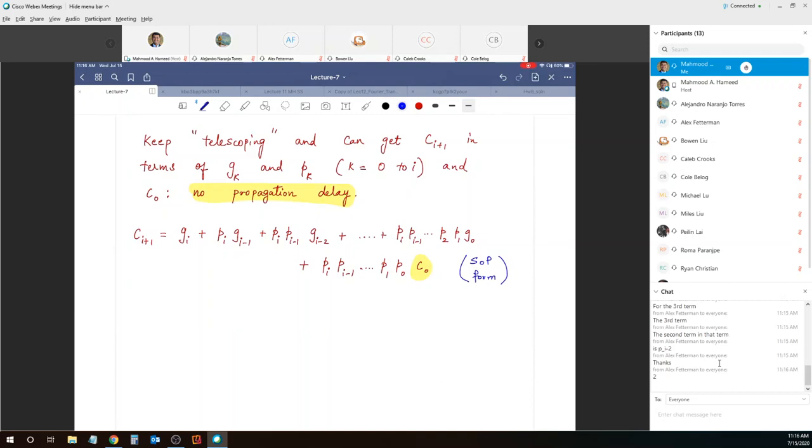The propagate function is also there. So the generate function requires 1 additional AND gate. The propagate function also involves 1 additional OR gate. That AND and OR function can happen simultaneously. So that goes from 2 to 3 gate delays. So 3 gate delays for the carry C sub i plus 1.